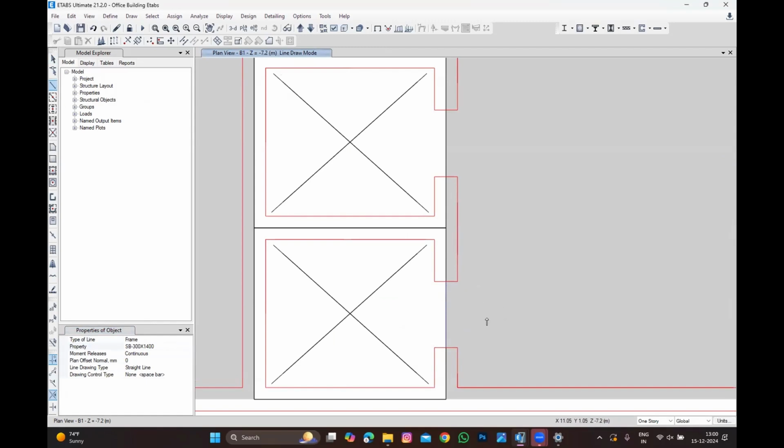But Sharjah municipality is a bit crazy. They will never allow us to model from here to here. They will ask us to model 50 times of diameter extension. You're getting a point, actually. Because when you're extending this spandrel beam, you're not going to stop exactly at the door opening, right? You will extend 50 times of diameter, isn't it?